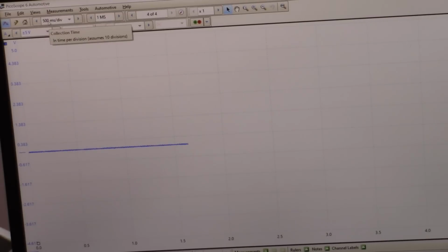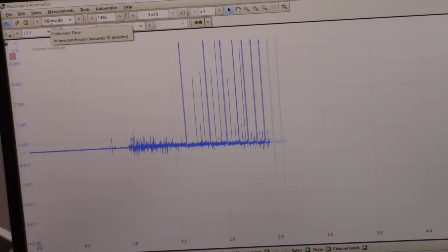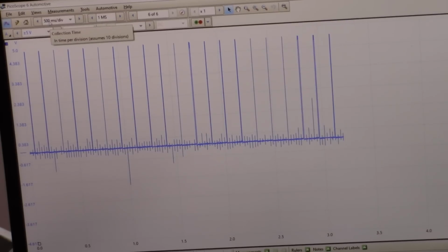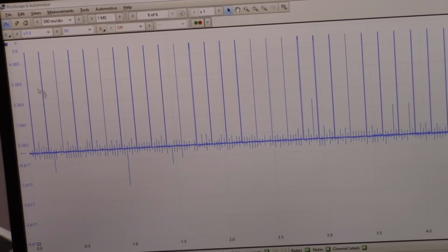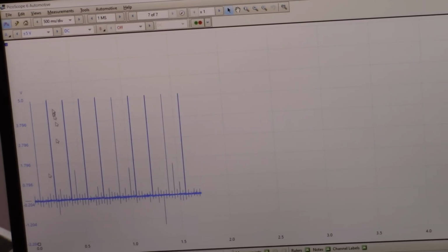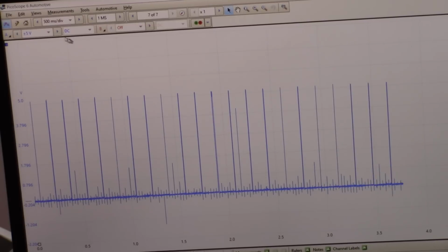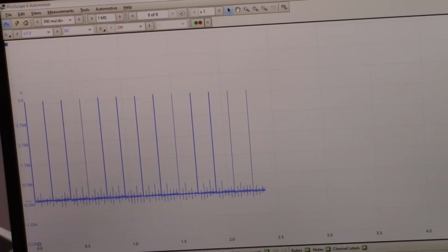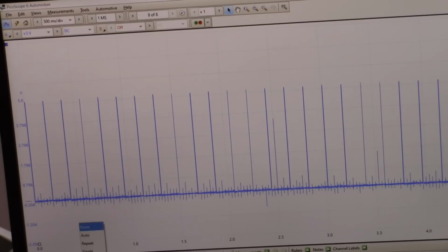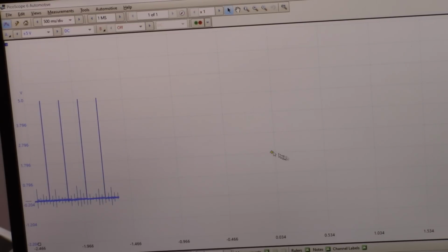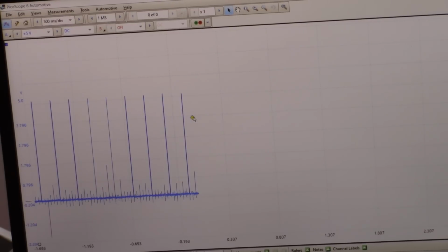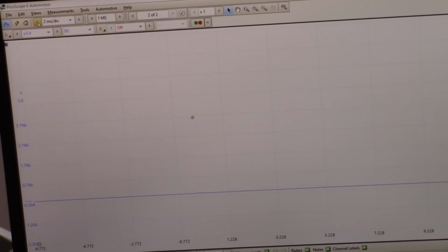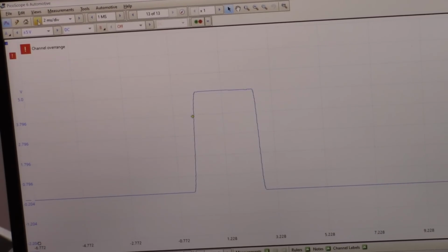All right, let's start the car. We should get a square wave. All right, and that is going to be a square wave. Okay, so we can see that maybe the 5 volts was a little aggressive. Some of these are just a bit over. If we narrow down, probably first we should set a trigger here. Be a little easier to see. And then if we split out our time frame, there's a square wave right there.